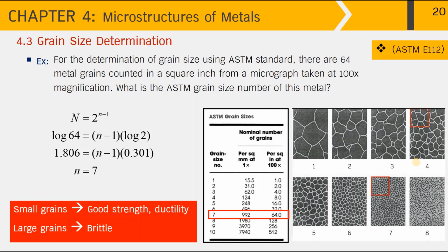That is, the grain boundaries will give strength to the metal while working at normal temperature. But if you remember in the case of the turbine engine, at very high temperature, the grain boundaries are not desirable then. So we have to understand the roles of the grain boundaries at different conditions and temperatures.